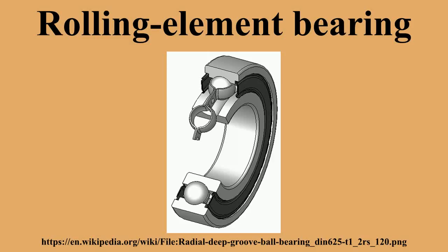Spherical roller bearings have an outer ring with an internal spherical shape. The rollers are thicker in the middle and thinner at the ends. Spherical roller bearings can thus accommodate both static and dynamic misalignment. However, spherical rollers are difficult to produce and thus expensive, and the bearings have higher friction than an ideal cylindrical or tapered roller bearing, since there will be a certain amount of sliding between rolling elements and rings.